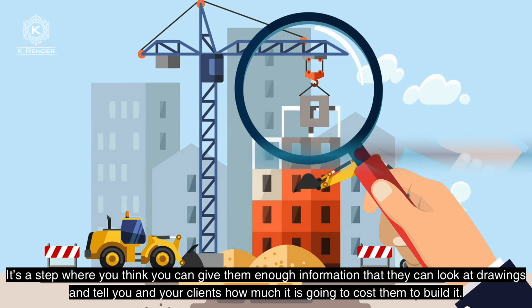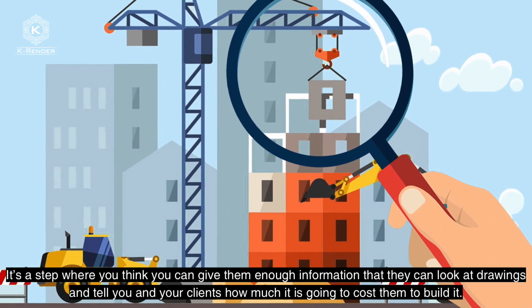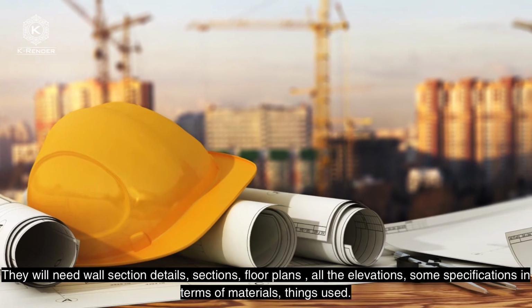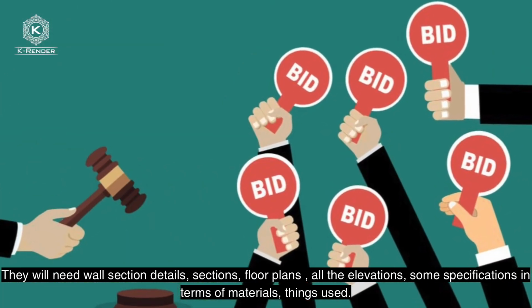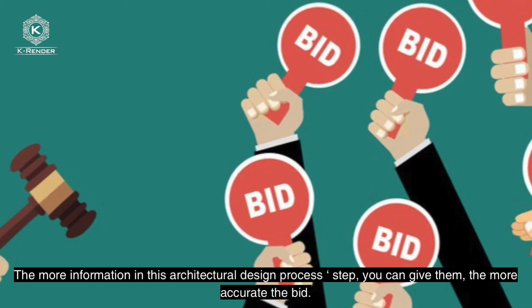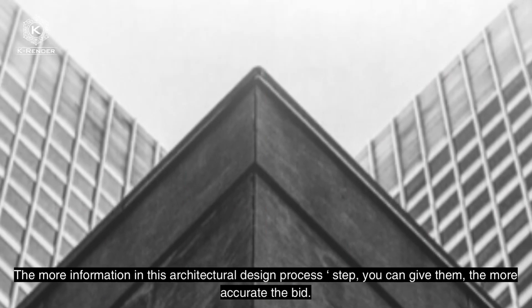It's a step where you think you can give them enough information that they can look at drawings and tell you and your clients how much it is going to cost to build it. They will need wall section details, sections, floor plans, all the elevations, and some specifications in terms of materials. The more information in this architectural design process step you can give them, the more accurate the bid.